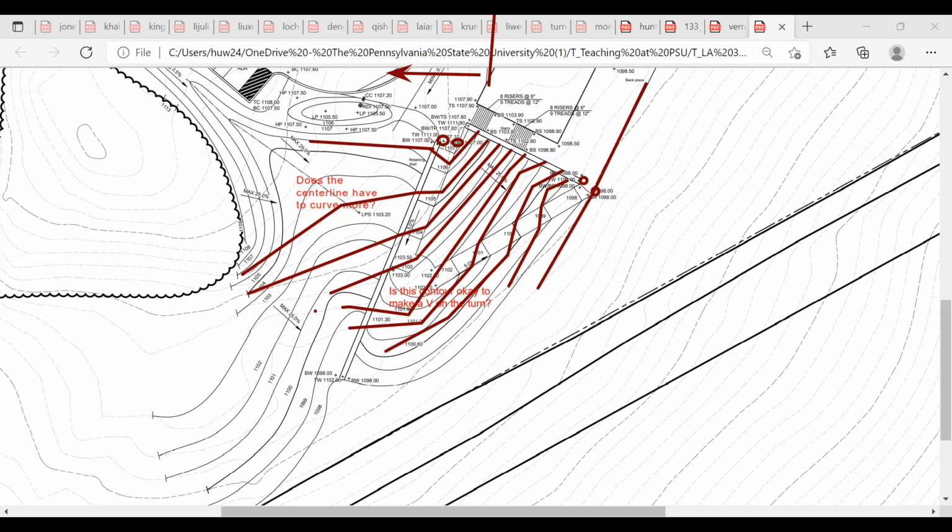You could start the 5% slope right in this area, so you don't need such a long ramp. It could save you a little bit of distance, but if you would like this whole area to be flat, which I think is a better design, starting the ramp exactly here, you would use the slope to calculate the top of the ramp. So those determine the slope overall, right?